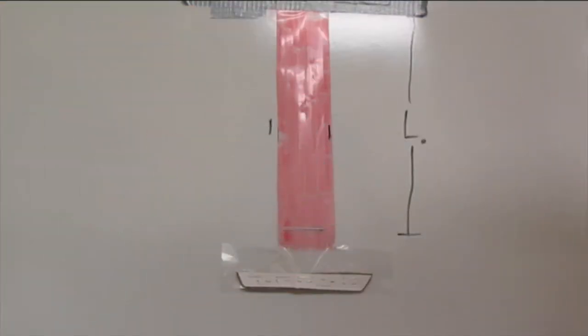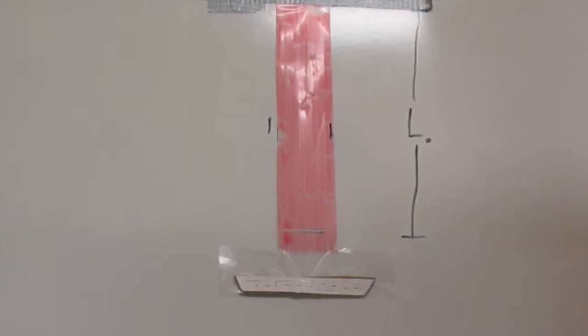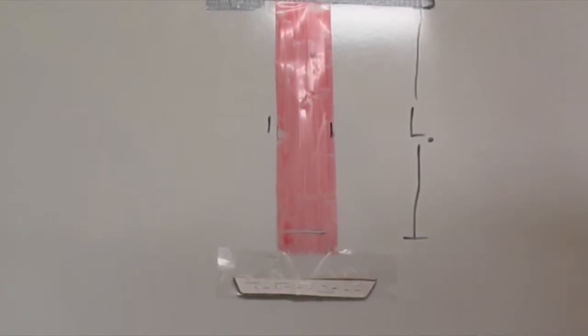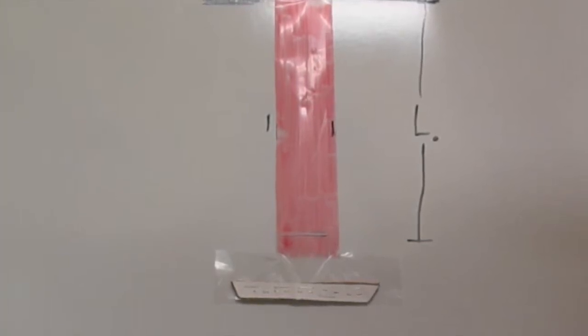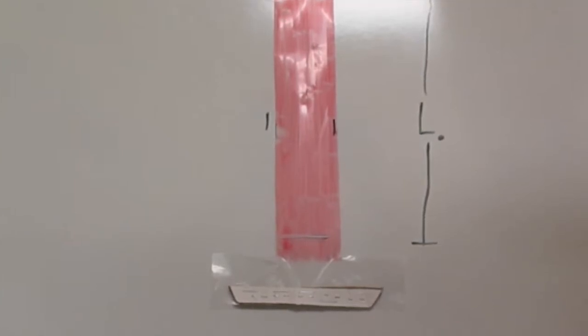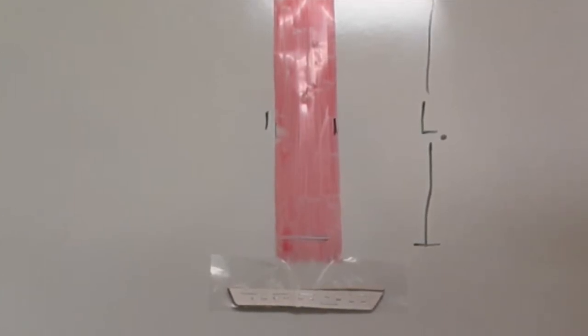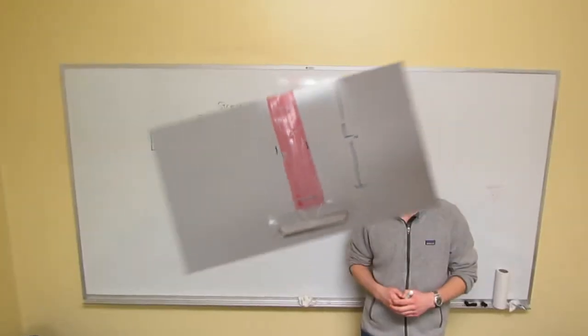As you can see in this picture, both the length and the width of the plastic had deformations. This demonstrates that the material went into the plastic region and holds true to what we know about solid mechanics involving ductile materials. An important element of any tensile test is Poisson's ratio, the negative ratio of lateral strain over axial strain. This is useful in solving for not easily measured deformations.